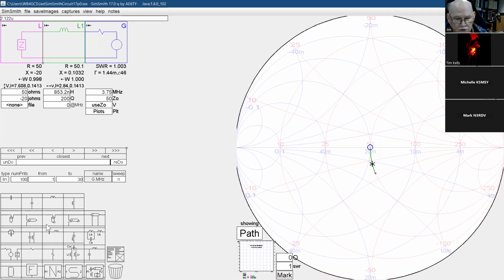You can use a series resonance circuit, a series resonant shunt circuit, a more complex circuit, all this stuff you can drag and drop. And these things with the funny names down here are where you build more complex networks that the documentation talks about. But the point is, you can start with a load, you can start with a generator, and you can start putting stuff in there.